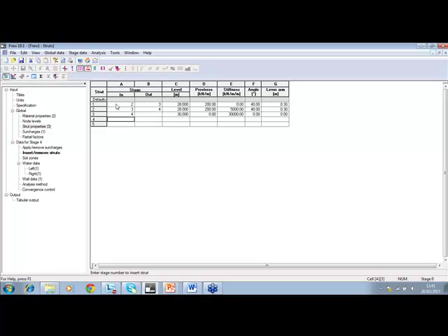Now the basement slab actually has the same properties as the ground floor slab, apart from the actual level. So what I've done is, as you can see, I've typed in equals twice in cell A4. And if I tab that, I get exactly the same properties for everything. So now I just need to change the level, because we're going to say that the basement slab for this example is going to go in at 24 meters OD. Okay.